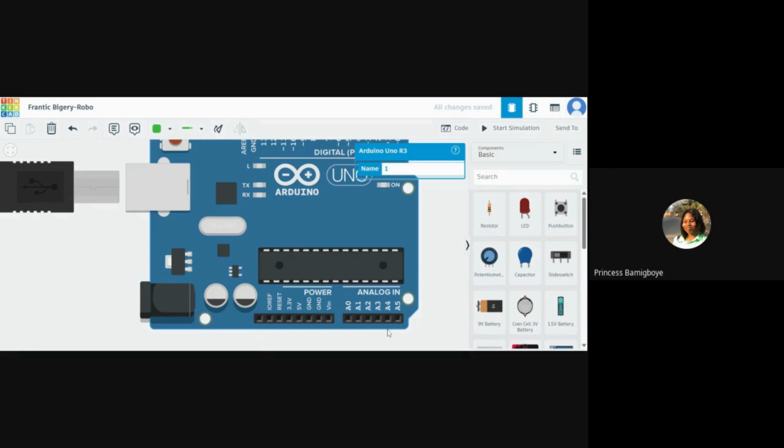There are 3 ways of powering the Arduino, right? You can use this USB, the thing that connects it to your laptop. You can use this jack, a power jack, which I will explain later. And another option is using this V-in pin. I will use this V-in pin for cases when I do not want to carry my laptop at every point in time. Through this V-in pin, I will connect the power source, in this case the battery, directly to my Arduino, and it will power it.